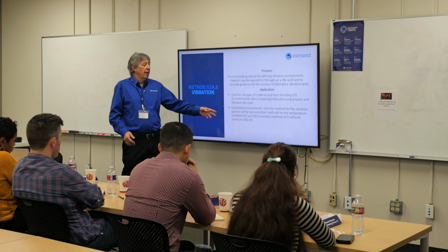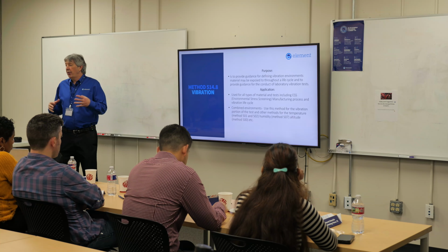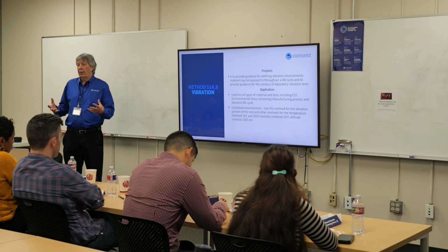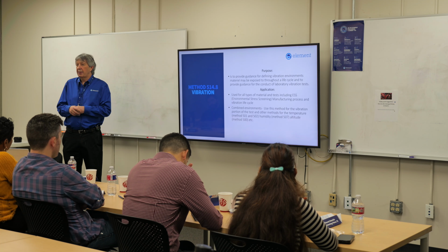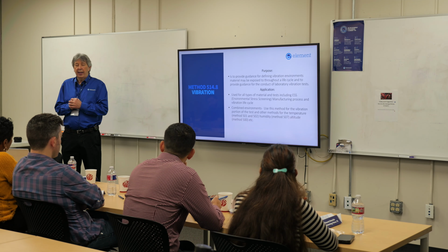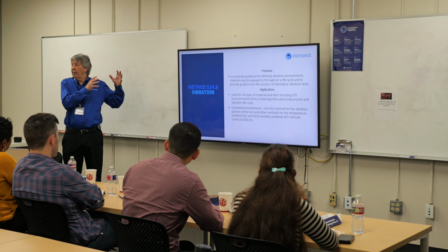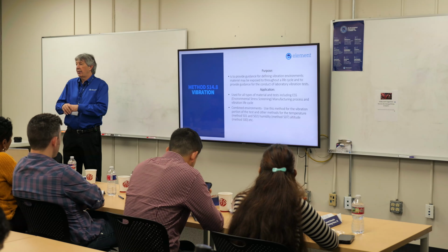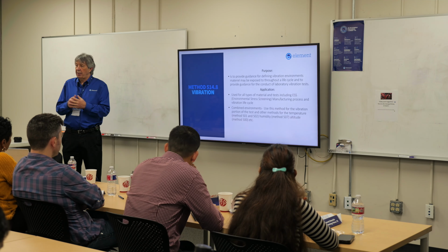Combined environment, use the method for the vibration portion of the test and other methods. So if your unit's on a shock mount and it's going to Alaska, we should run it at ambient and cold because obviously your shock mounts are going to change your resonance and things like that. So some thought needs to be put in there. 810 doesn't say you have to do it, but just in case, so some thought. Most of the time, vibration 810's running at ambient because you have your standalone temperature test. But if you're shock mounted, it might be something you want to think about because your shock mounts are going to change based on temperature.